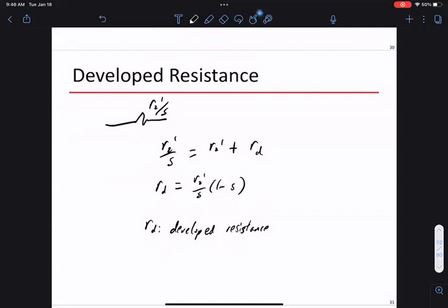Yeah, right. So the question is, where does the prime come from? Prime comes from the secondary side of a transformer. Because this is not an actual transformer, it's an induction machine, we'll never talk about the actual transformer ratio or this kind of thing. So all the secondary side will be the prime numbers. If things are a little bit inconsistent, just think of this as one circuit. So this RD, for example, sometimes it has prime, sometimes not. And you'll find different books and papers have different conventions.